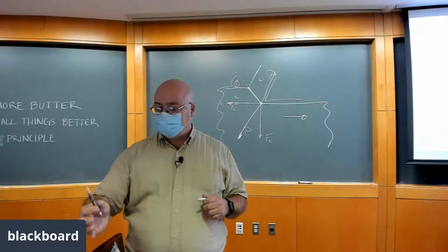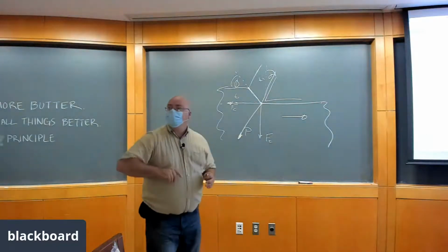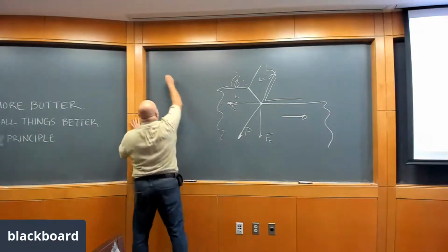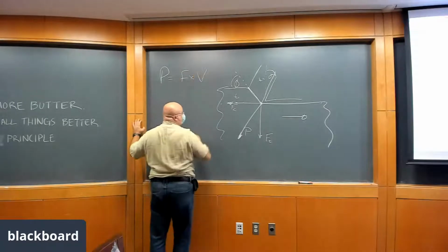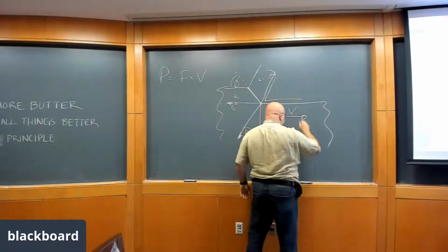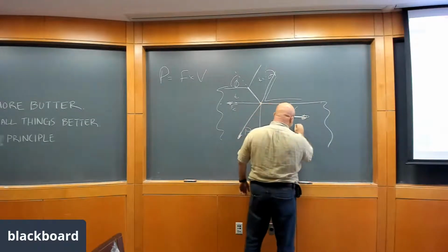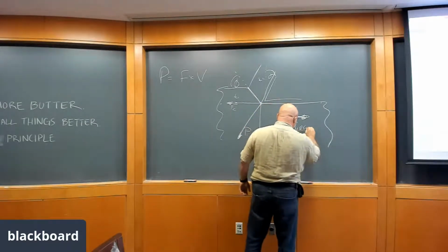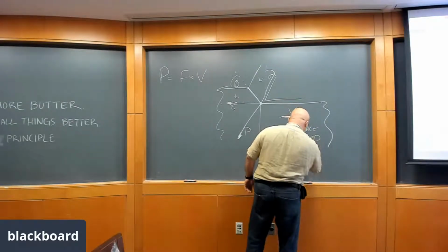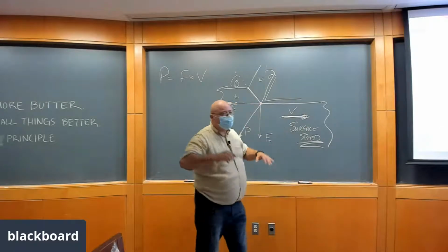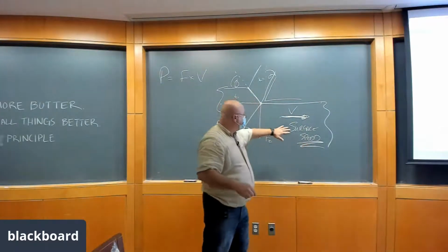Is it that the force times the velocity, since the tool is moving in that direction? So power equals force times velocity. This is our velocity over here, right? And this is the surface speed. So our surface speed, that's the speed at which the cutting edge of the tool moves through the workpiece. What does surface speed depend on?